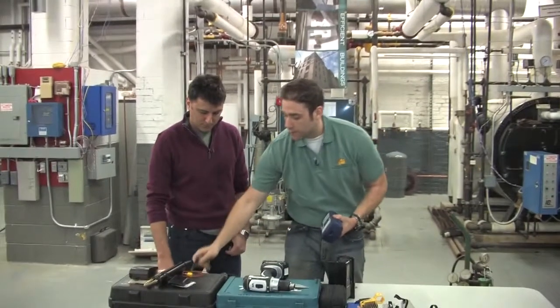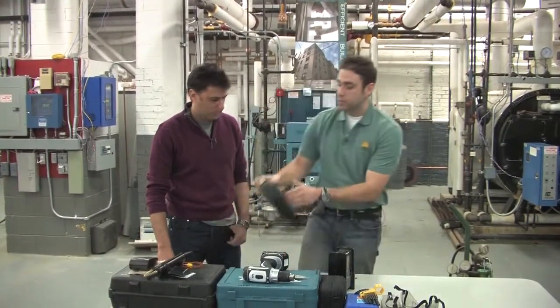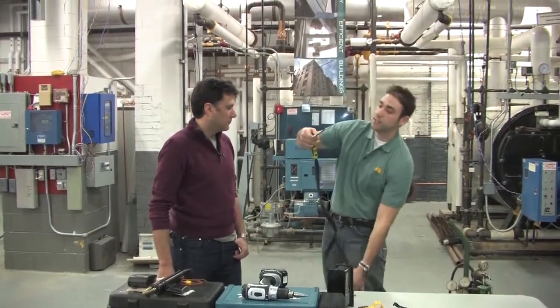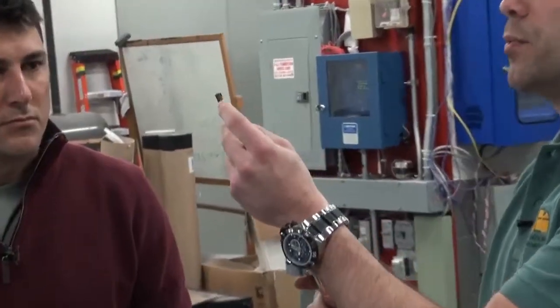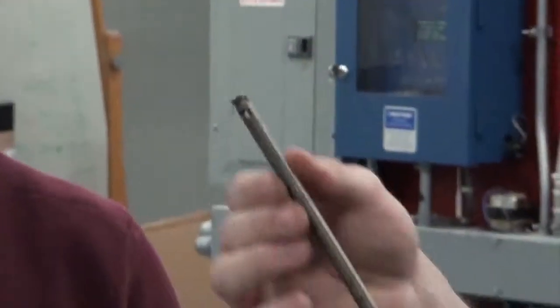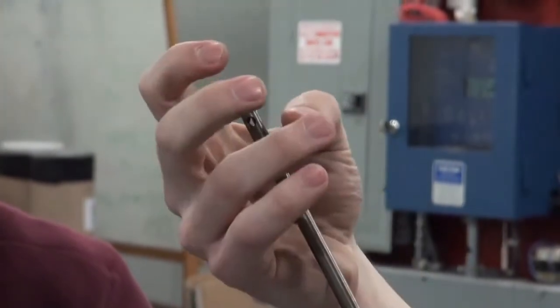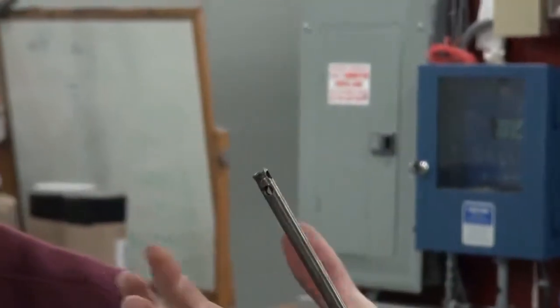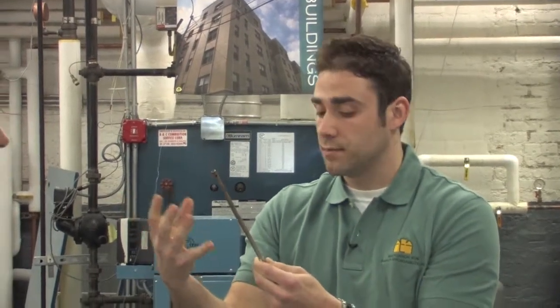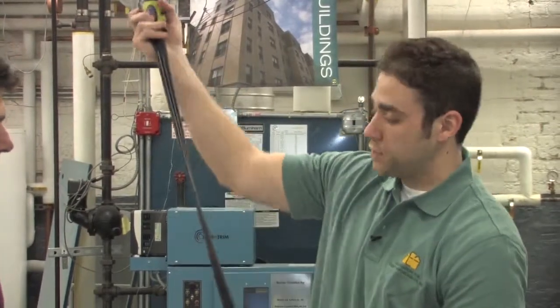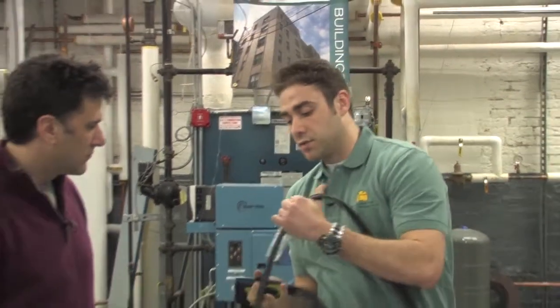The analyzer has a little probe that's going to be connected to it. At the end of this probe there's an opening. And what happens is there's a vacuum that's being pulled through here. So these little openings on the side pull the combustion gases through from all directions. That's also going to measure the temperature of the flue gases as it goes through to be able to do the efficiency calculation. This all gets connected into a hose system, which goes through a little filter at the bottom.